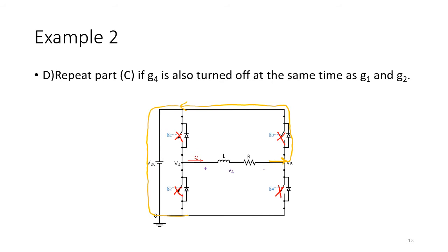And this is a circuit. We need to close the circuit. So it comes back. Now, at this point, it needs to go back to close the circuit. Can it go through the diode of G2? Yes. So it goes like this. And here, like this, the loop will be closed. And then the current will circulate like this.